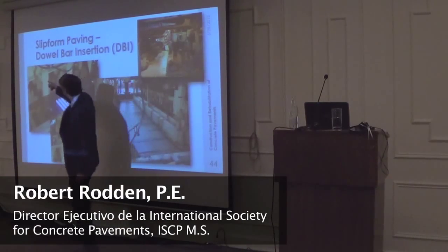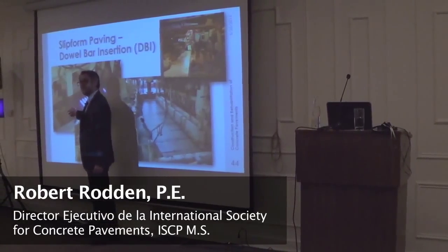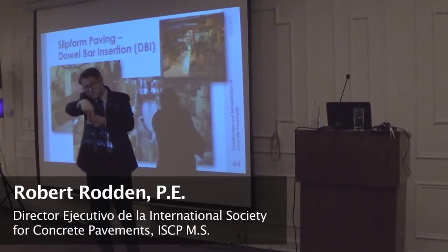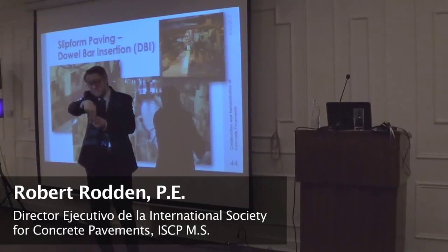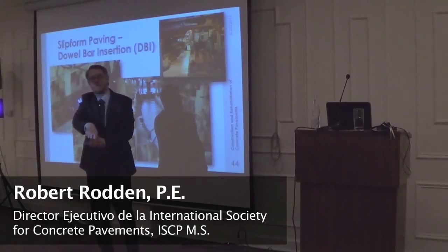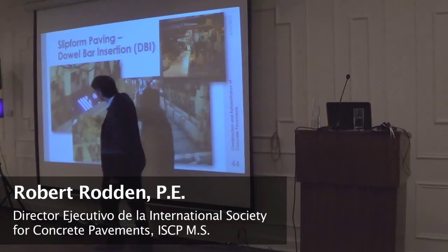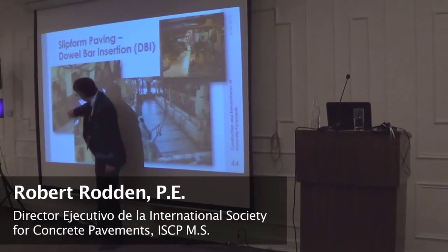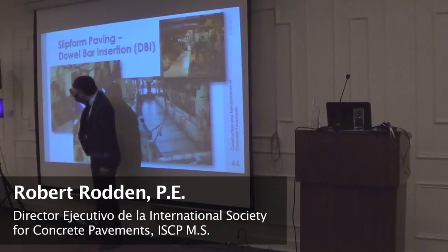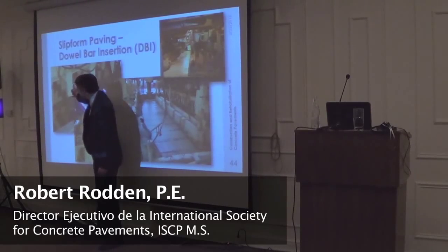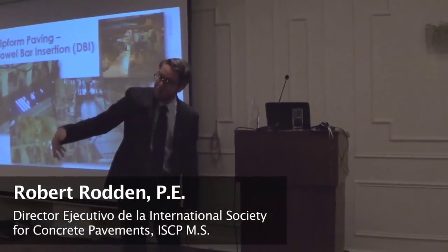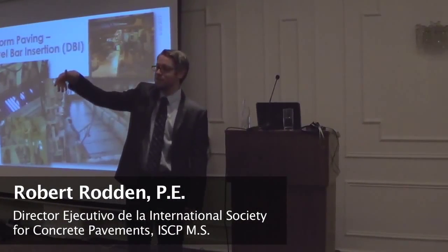That has forks, four of them attached to it. So these four forks go down, engage the round dowel. That beam vibrates, and it vibrates them down to the required depth. The required depth being this distance right here, from the point where the dowel will be fully engaged, the apex there, the top, to the full depth of insertion. So it's that simple. Supply the dowel bar, push it down, vibrate back out.